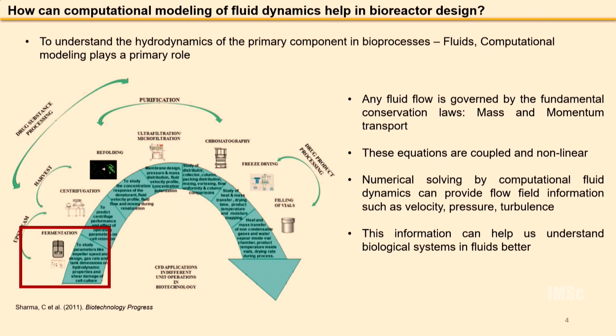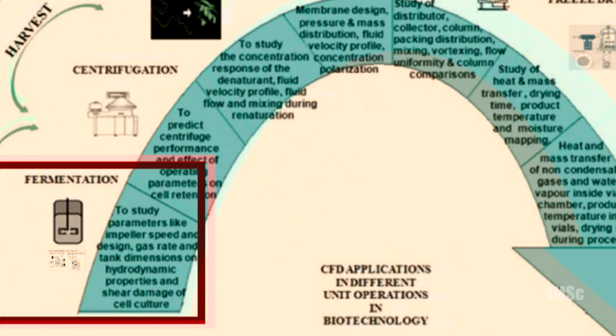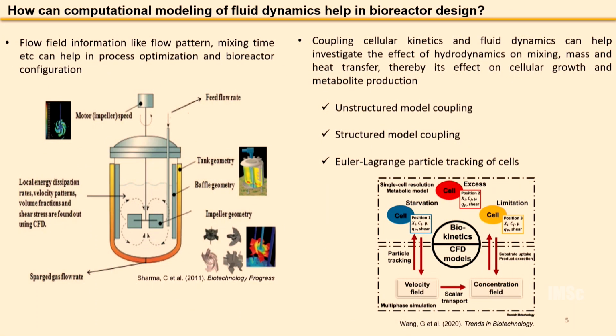Here we can see there are a lot of applications for CFD in biotechnology, right from fermentation to the downstream processing, but I'll be focusing only on the fermentation aspect, which is bioreactor design. With respect to bioreactor design, we can get information like mixing time, the flow patterns and different bioreactor design aspects such as the impeller design, sparger design, and operating parameters such as the impeller speed and so on. Apart from that, coupling the kinetics of the cell with the fluid dynamics can help us investigate the effect of hydrodynamics on the mixing and mass transfer.